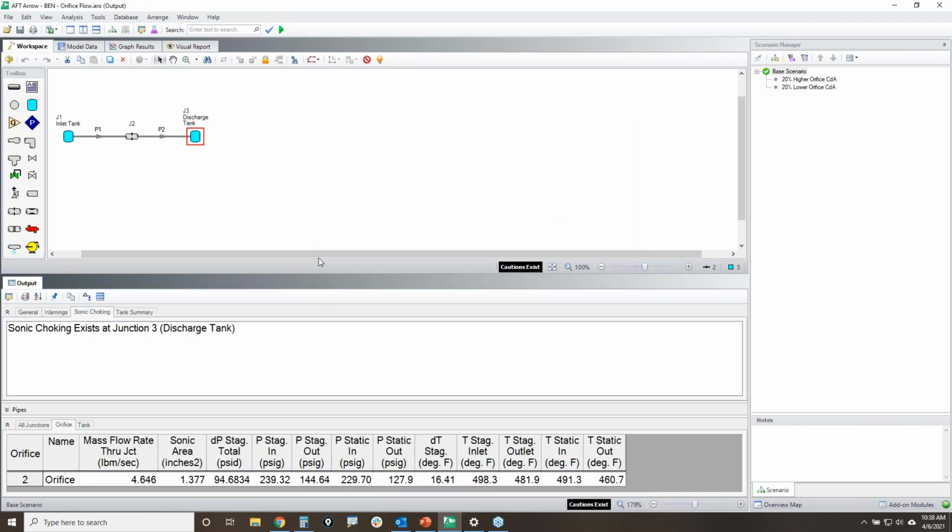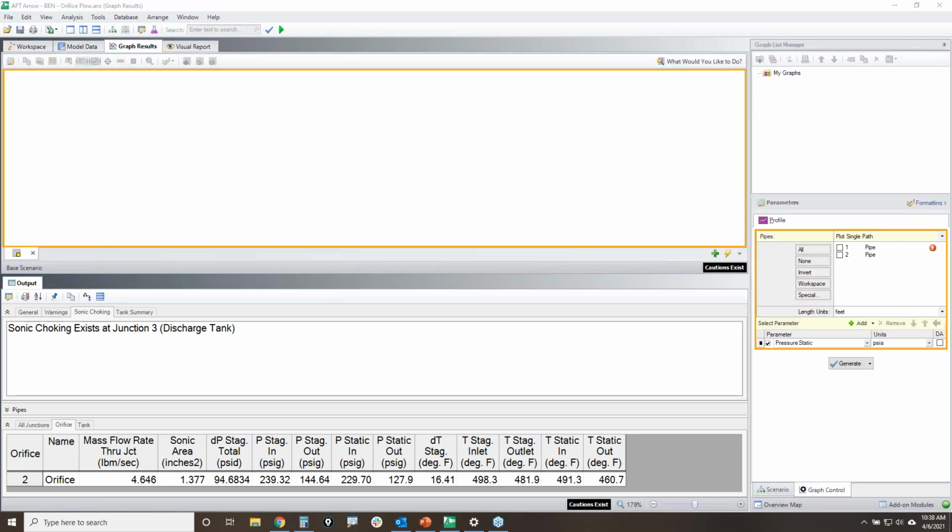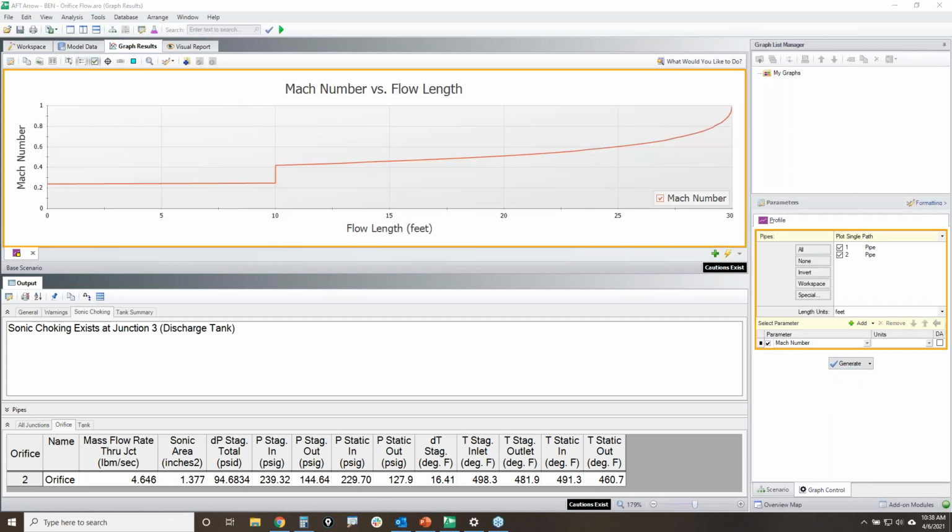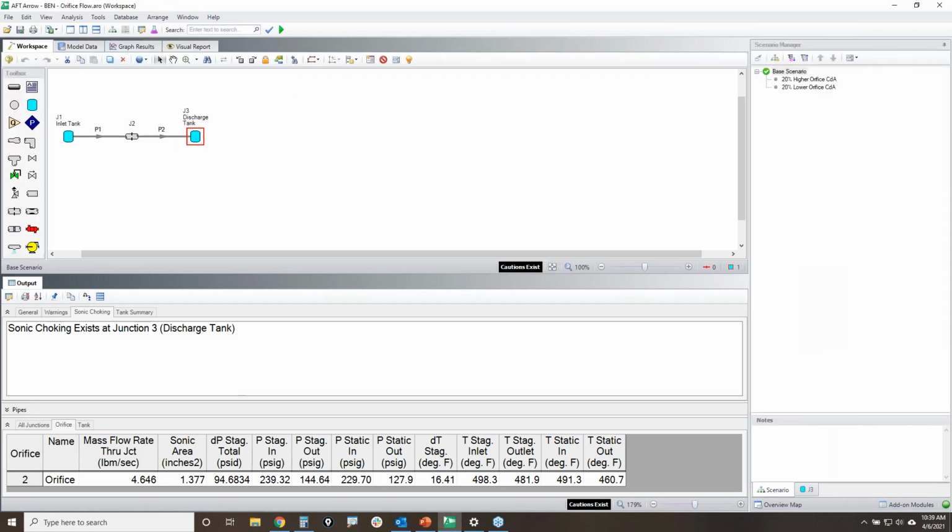So that's a difference of 1 psi. In a difference of 1 psi, we went from subsonic to sonic. And so it very well can make a significant difference. This is what I like to do to help illustrate the point that if you're trying to increase the flow rate of your system, lowering the downstream pressure is not going to help you get additional flow when you are sonically choked. So what this means is that, let's say it's 88.5, okay?